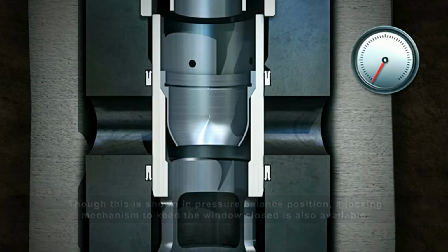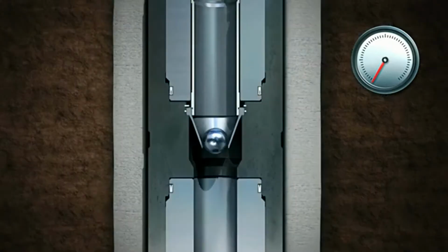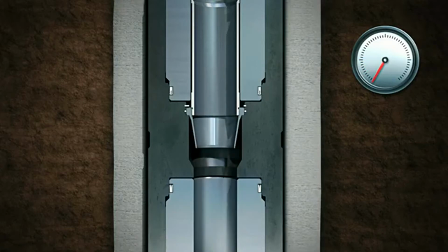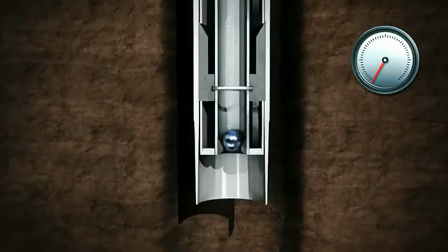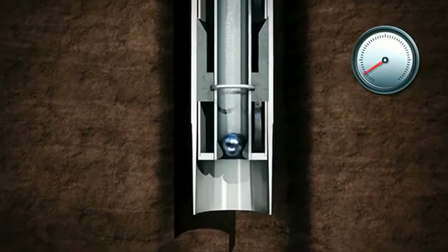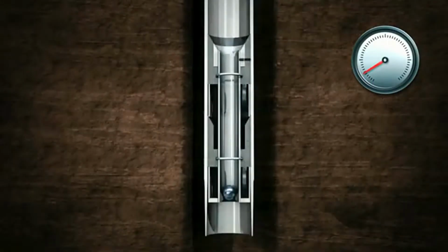The ball will fall to the Blackhawk diverter test device. From the surface, 1000 psi is applied to make sure the Blackhawk diverter is closed and tested. After testing, continue to increase the surface pressure from 1800 to 2400 psi to yield the seat in the DTD. The ball will fall until it reaches the seat in the autofill float collar. Surface pressure of 300 to 600 psi is then applied to activate the float collar, preparing the wellbore for the